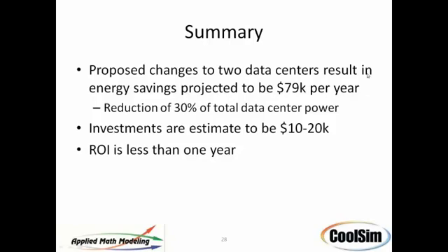But you have to keep in mind the fact that the racks are going to be involved in this as well, because there's a delta T across the racks, and it depends upon what the flow rate coming from the cooling system is versus what the flow rate demand is. And if those two are closely matched, then whatever the delta T drop across the cooling system is going to have to match or come close to the delta T increase across the racks, across the equipment. So it all depends upon how the flow rates are varied as well. And the geometry of the room, yes.